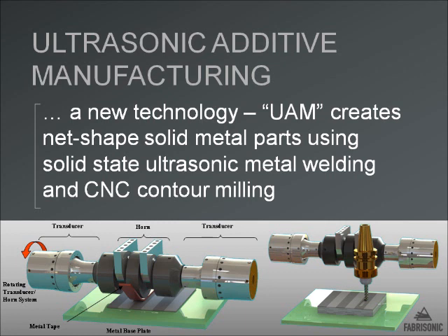These are piezoelectric stacks that convert electrical voltage into mechanical motion. These transducers push left to right the center ultrasonic horn. This is an acoustically tuned device that is designed and built to vibrate at a very specific frequency, 20 kilohertz. It vibrates left to right at about 30 to 40 microns, creating a solid state weld.